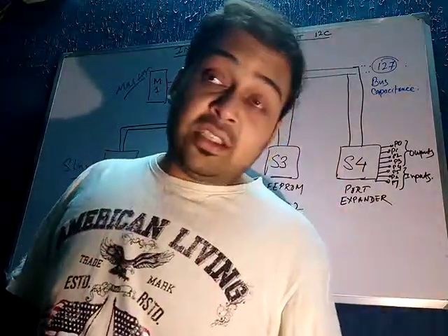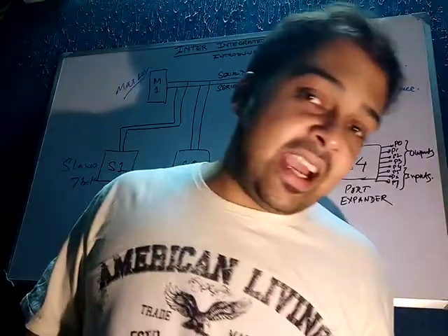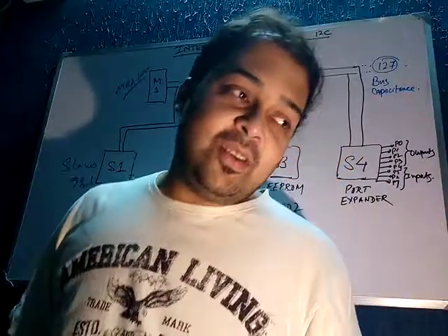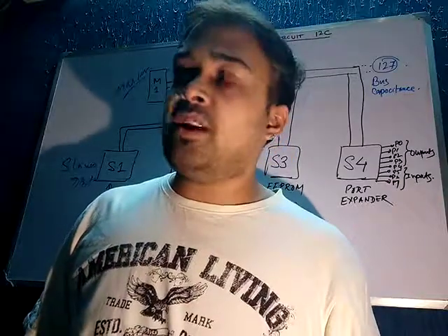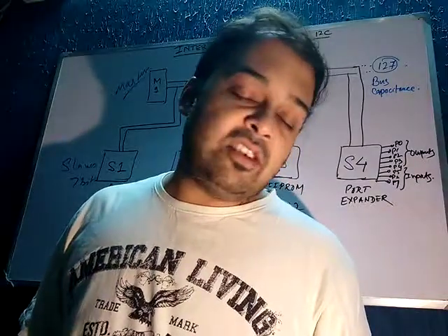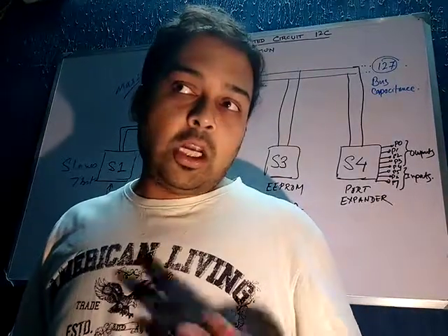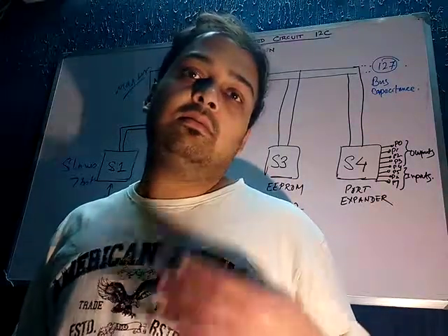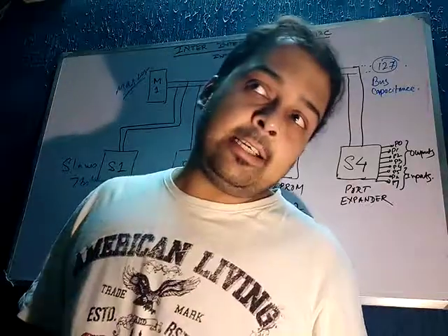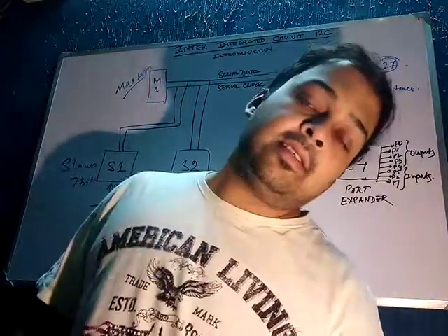You can't just have an I2C line running 10 kilometers, send data, and say, oh my god, why is it not reaching there? No, it will never reach. You have to calculate the clock speed, at what speed you can send data depending on the bus capacitances.